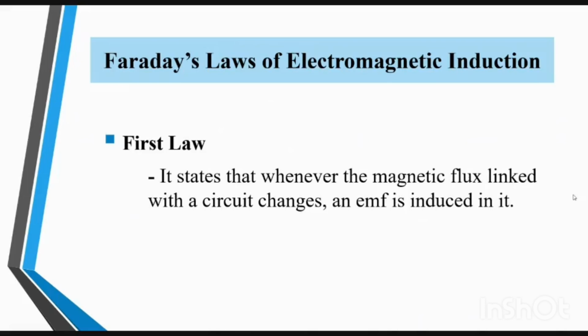Coming to the important section, that is Faraday's laws of electromagnetic induction. First law. It states that whenever the magnetic flux linked with a circuit changes, an EMF is induced in it. Or whenever a conductor cuts the magnetic flux, an EMF is induced in that conductor. This is the first law.